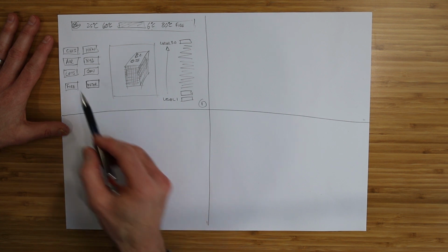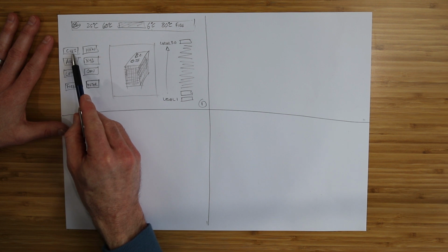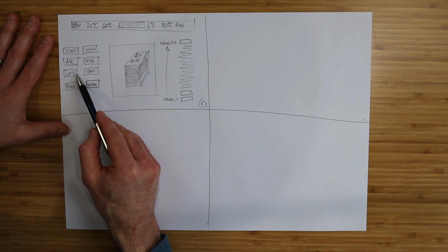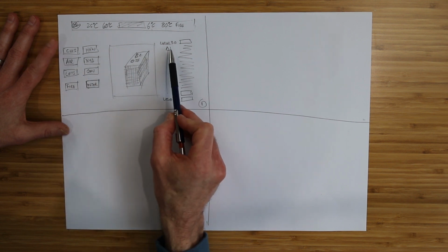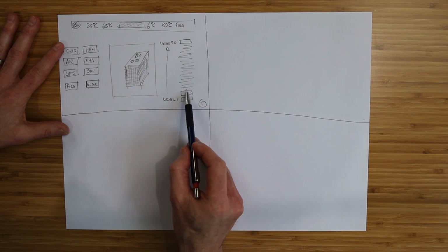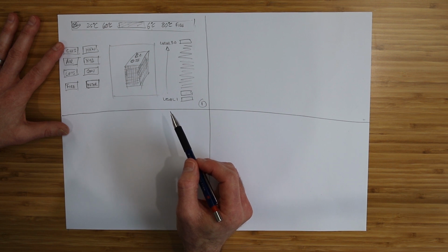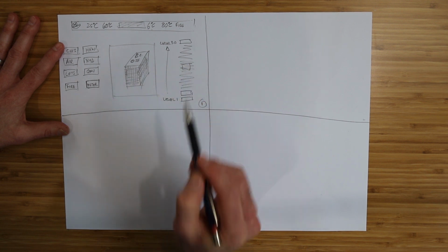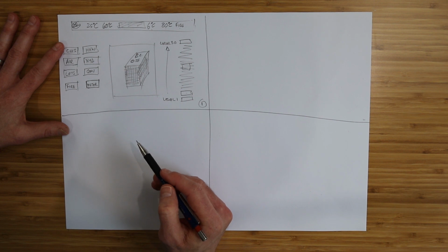What we typically have is some buttons that link to all the main systems. For example, the chiller management system, heating hot water system, air handling units, hydraulics, lifts, generators, fire. And then on the right-hand side, sometimes we have buttons that link up to all of the 30 levels. So if you're going to do some monitoring or investigations or some diagnosis on level 10, you click level 10's button and off you go to the floor plan, and you can navigate through the VAVs or the chill beams and package units and all those sorts of things.